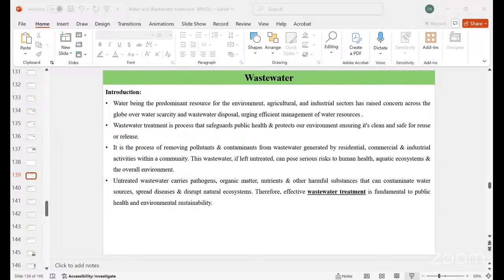Next, the flow equalization tanks. Before going to flow equalization, let us describe this diagram, which is the grit removal. Due to gravimetric settling, there is a huge amount of black dots coming. These are the grit settling at the bottom, called sludge as well.